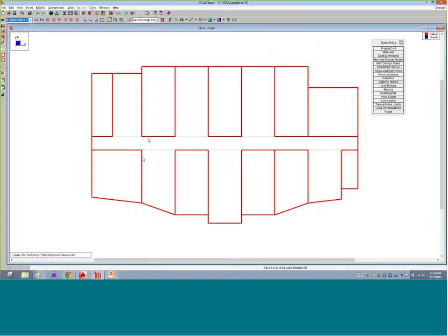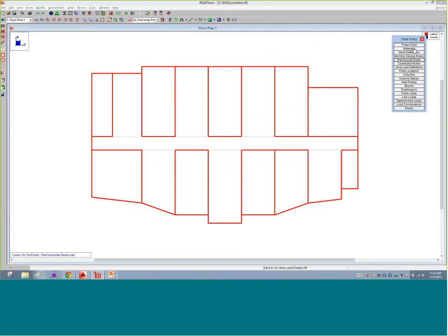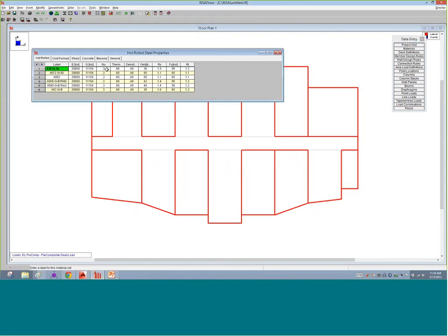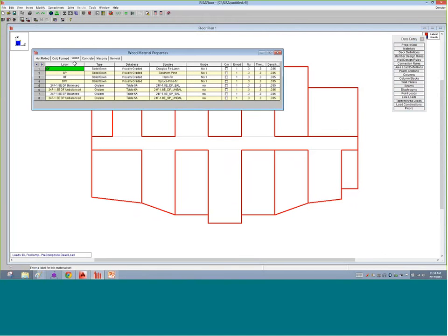Now we've added some cool enhancements to the databases, and I want to show you guys. What we've always had here is if you go to materials database, and you open up that spreadsheet, you can see the wood, and we've got a couple changes. You've always been able to look at the wood species over here in the wood spreadsheet. Take a look at the Doug fir, southern pine, and see some of the glulams we have. It looks a little bit different than it used to. We have some different options here. When you say type, the program is going to ask you what kind that is. Is it solid sawn, glulam, SCL, or custom? You can see if you choose different types of things.